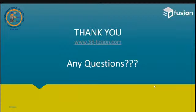Yes. So you can imagine if you are making a cube. If you're trying to print a cube, so the first layer you will see only a square shape. The laser will first of all go to the boundaries of that square, and will scan that area, and then it will fill in the inside area. So the whole square will be fused together on the first layer basically.